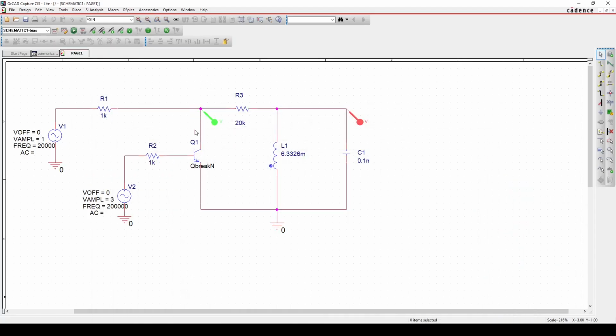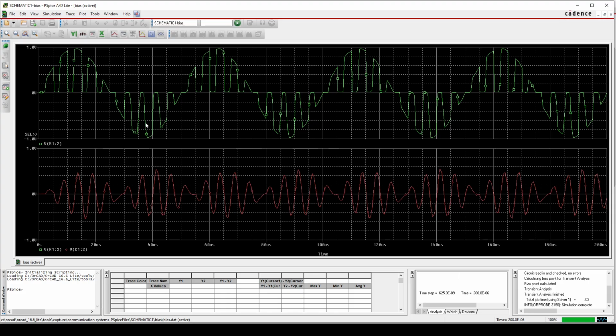Okay, so remember this green voltage marker and this red voltage marker. Alright, so this green trace is the result of switching the BJT transistor on and off to create that virtual ground at the message signal. And then this is in a similar appearance to the message sine wave being multiplied to the square wave in the time domain. And then after passing the signal through the bandpass filter, we're going to have the DSBSC signal right here.